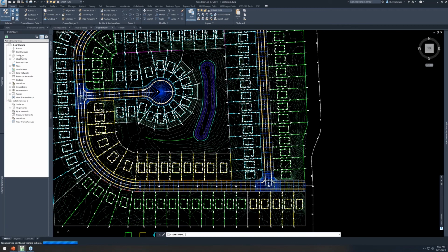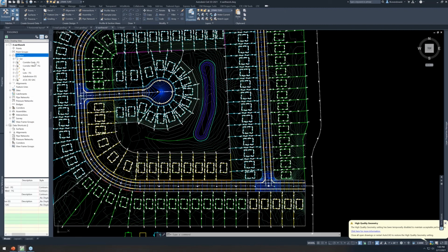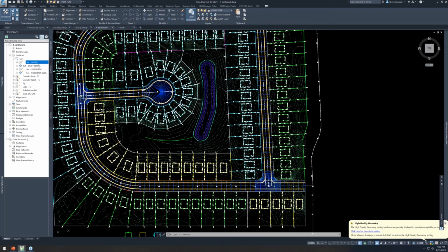If I look at my surfaces here, it's making a surface folder. It's making a depth surface, and then ultimately a subgrade surface. This is the surface that's linked to finish grade, but it's brought down based on those polyline depths. And then ultimately we get an earthwork volume surface, which contributes to those individual cuts and fills. Now, like I was showing you, we go and change road designs, we change lot designs.